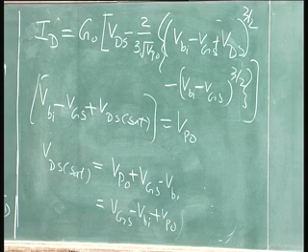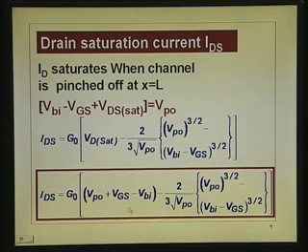Okay. That is what we are doing there, because everything we want in terms of these quantities. Now, notice that we are able to eliminate V d sat from that. So, we are trying to put everything in terms of V b i and V g s and V p 0. Okay. So, this is the particular term that we get now.